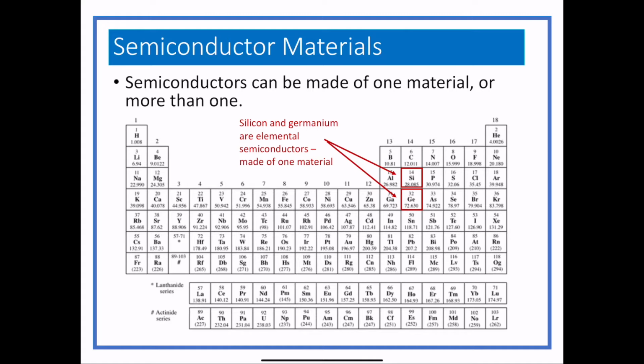The lady who had ordered them was talking to me, and they really didn't know anything about semiconductor devices. That's one of the reasons I was there, to do the electronics courses. And she said, well, we went through and we were checking these germanium diodes, and they have a forward voltage of like 0.68. And I said, no, you can't have that with germanium. Germanium has a forward voltage of about 0.3. And she said, well, we checked them, and that's what they came out. So that's just what I'm going to tell the students. Like, no, you can't do that. They aren't real. And they kind of didn't believe me. I brought one of them over here and put it in a curve tracer, which they didn't have over there. And it didn't even look like a diode at all.